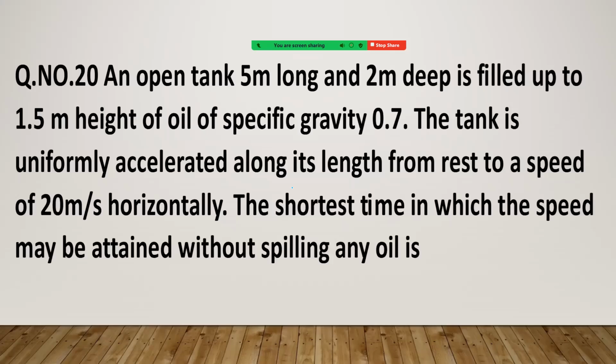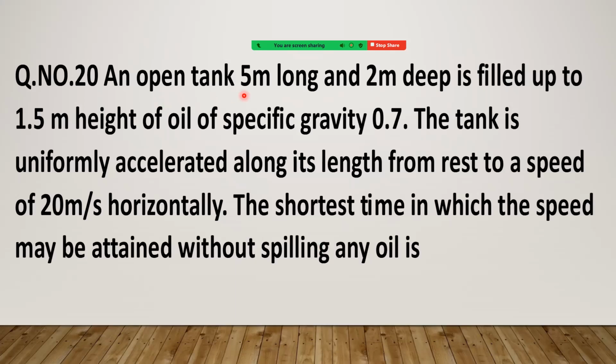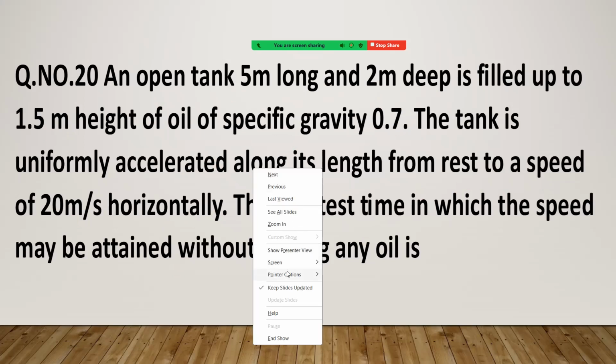Now focus on the given problem. The length is given, the depth is given, filled up to 1.5 meter. Specific gravity is not required for us. It accelerates from rest, and we have to reach a velocity of 20 meter per second. The shortest time in which it may be attained without spilling any oil. Use the results which we got.